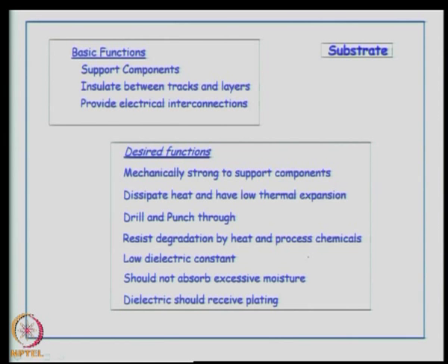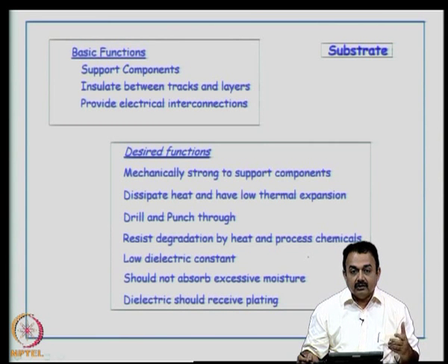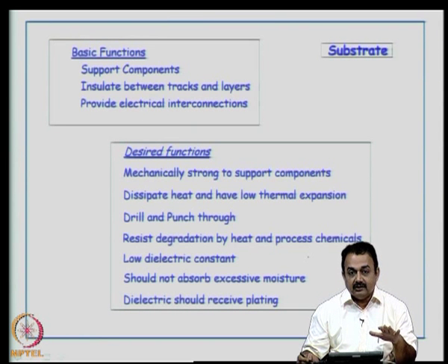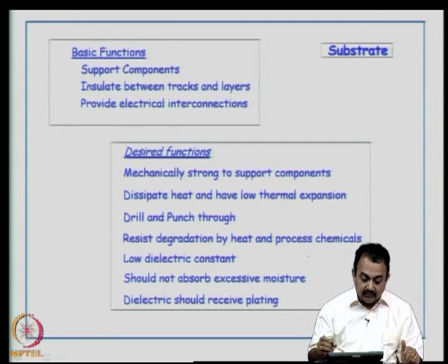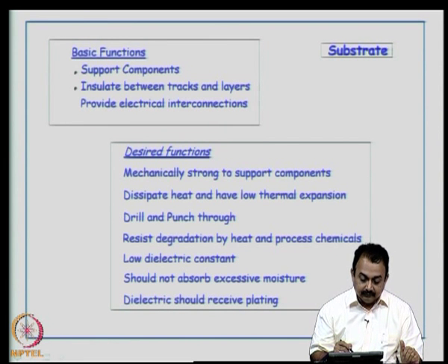What are the functions of a substrate? The basic function of a substrate is it supports the components, right. When you finish a PCB, you are mounting the components. So, it is very rigid and it supports the components to be placed and interconnected by using copper tracks. It provides a very good insulation between the tracks and the layers, right.